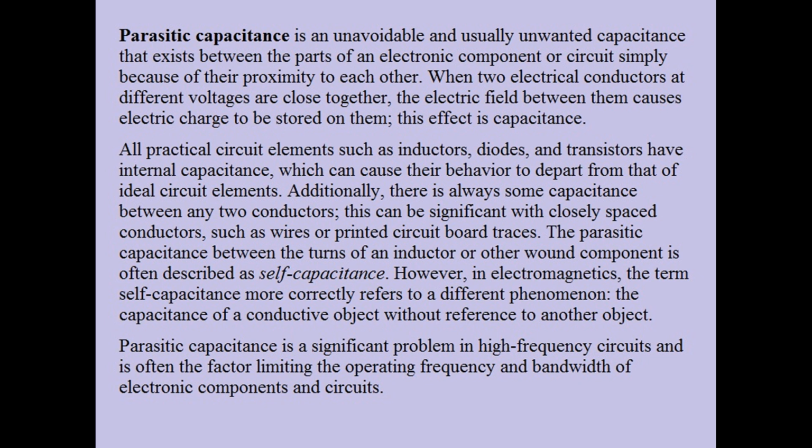However, in electromagnetics, the term self-capacitance more correctly refers to a different phenomenon, the capacitance of a conductive object without reference to another object. Parasitic capacitance is a significant problem in high-frequency circuits and is often the factor limiting the operating frequency and bandwidth of electronic components and circuits.